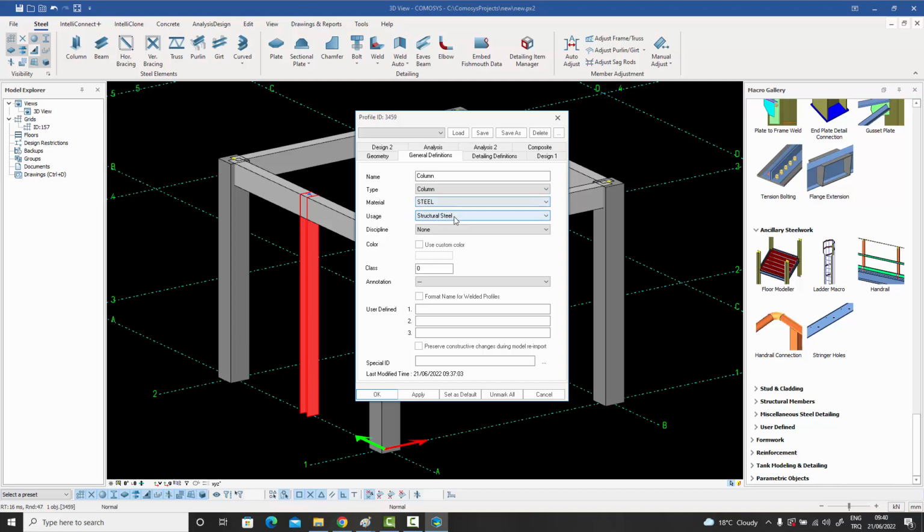Now I said that all the cast in place concretes will be merged together. Similarly, all the precast concrete parts can be made a separate group. They will never merge with the cast in place ones. Similarly, the earth related parts will form their own union or merged group on the drawing side, and just the same is true for the grout. But more often than not, you'll be using the cast in place concrete one. So let's focus on that. So anything which it finds to be cast in place concrete, it will merge on the drawing side.